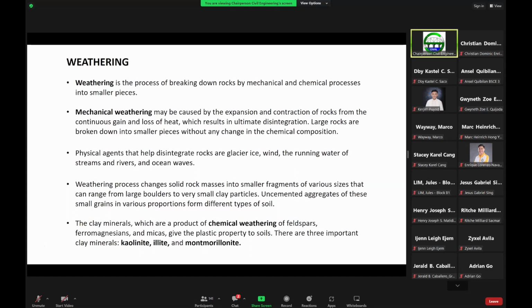differently. For example, when you have a liquefiable soil, usually that happens below the groundwater level. But when you have an expansive soil or a collapsible soil, usually that happens above the groundwater level. But we have many ground improvement techniques that will address such problems. Normally, these ground improvement techniques are discussed in the masteral degree program for geotechnical engineering.